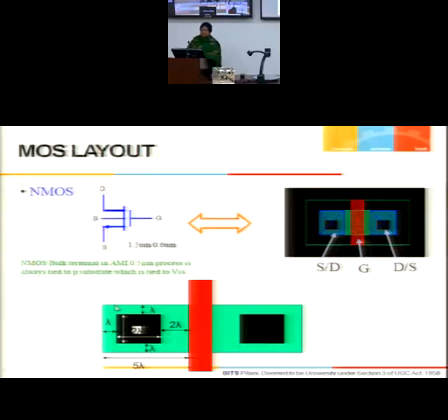Everybody should have it in mind. So this lambda is 1 micron. This width is going to be 80 micrometer. And this can be minimum, say 5 lambda or 5 micrometer. Clear? And channel length is say 2 micrometer. Clear? Or 2 lambda. May visualize this in mind. Everybody has visualized. Now this 80 micrometer.